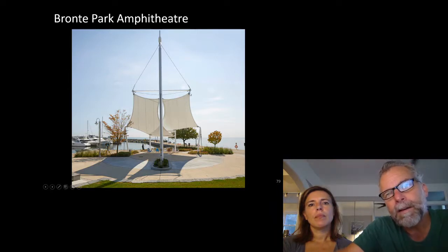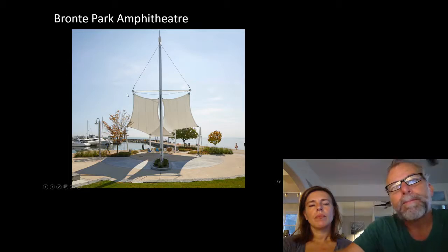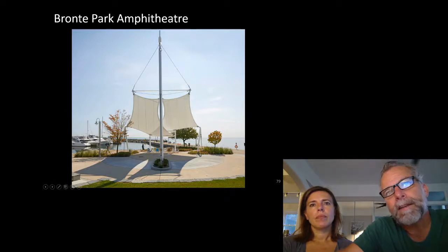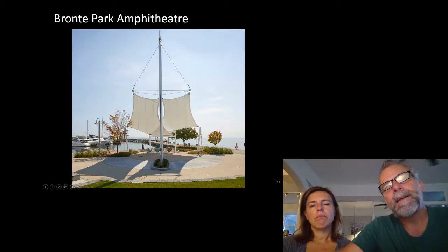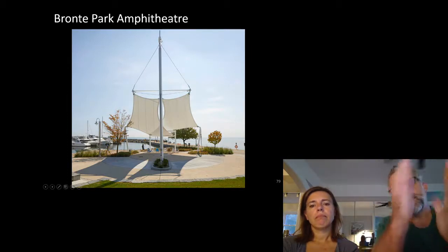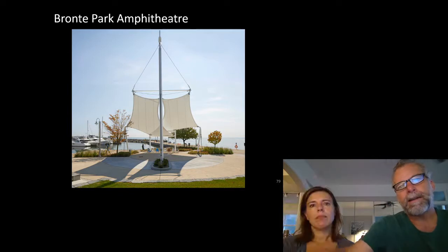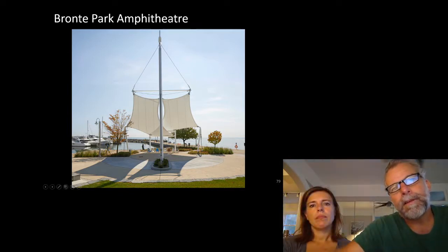It just floats there and pushes out these two points, and is held in space by tension cables. A few other interesting details: there was a desire to articulate the top of the mast, so we did a little step down to a smaller size, and then up at the top it offset and continued on at a smaller size.